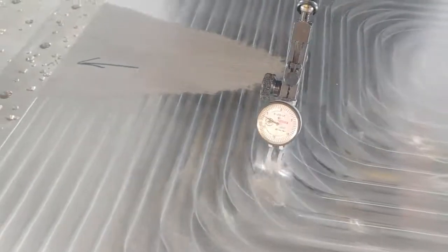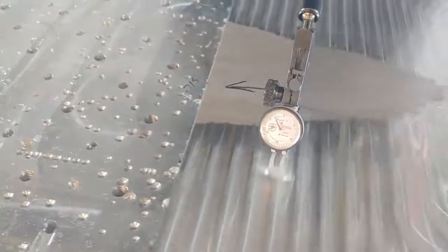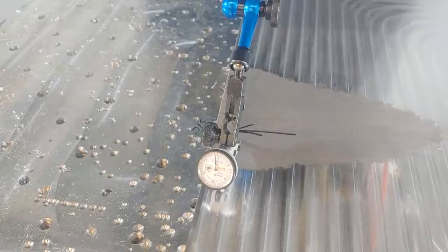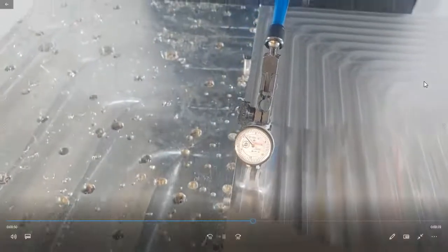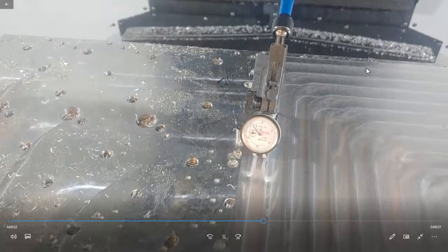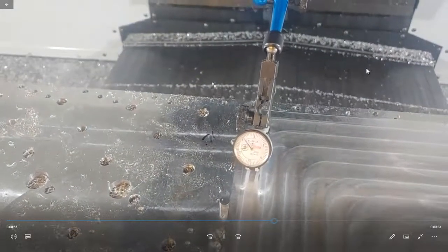Now, the rest of the surface is staying well within a thousandth of an inch. So this moves across, we get a little high spot, so it jumps up 2 or 3 thousandths and then drops down. So at this point I can safely say that this plate, even in its current condition, has a tolerance zone of 10 thousandths on its flatness for this surface.